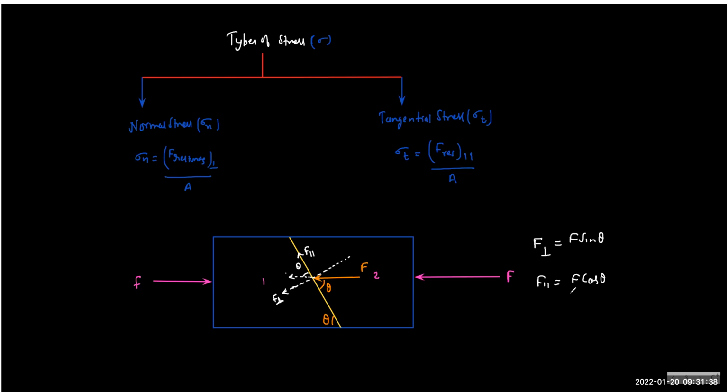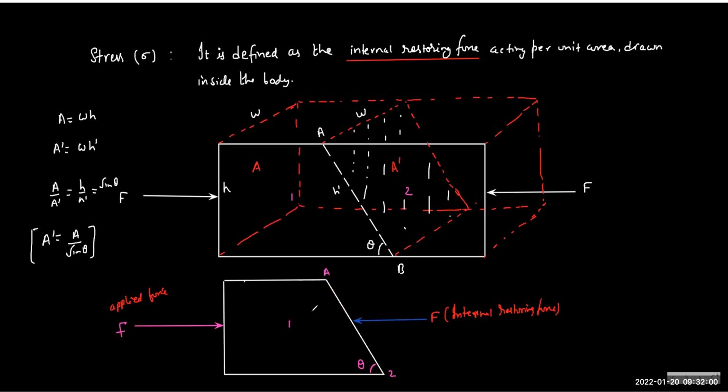And to know the internal force at a given cross section, you must draw a separate FBD for the part of the body which can open that surface, or expose that surface, to the viewer. It means I will just do half of it, the way I did on the previous page, like this. So always, to know the internal force at a given cross section, you must cut from there and then draw the FBD.